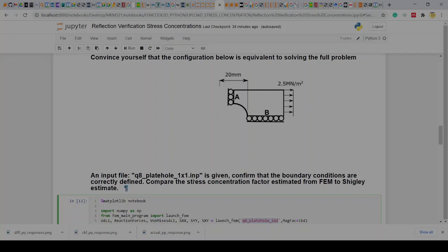And then because I'm using this 1.1 input file, that's a single element there. The total load over that single edge is then 50 Newtons. So I expect to see 1/6 times 50, 1/6 times 50, and 2/3 times 50 for the 3 nodes of that single mesh. Okay, that's one aspect.